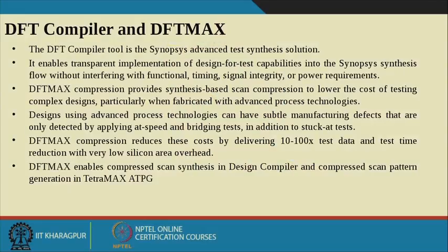This DFT Compiler tool supports the Synopsys advanced test synthesis solution. It enables transparent implementation of design for test capabilities into the Synopsys synthesis flow without interfering with functional, timing, signal integrity or power requirements. DFT Max is another tool set of Synopsys.